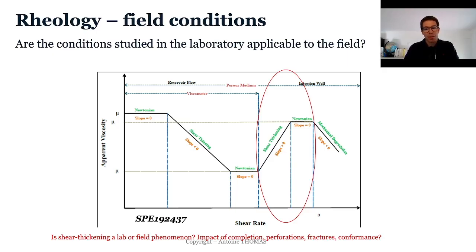So the next step is polymer-related mechanisms. And it's very, very important to understand the rheology, and especially how it will be in the field compared to the lab. So in the lab, very often what we tend to do is to run core floods at fixed velocity in the beginning to check propagation and retention, and then making in situ rheology profile by increasing the velocity. And so typically what you will see is at low velocities you have what's called a Newtonian plateau, which is once you have low shear, which should determine at your reservoir conditions.